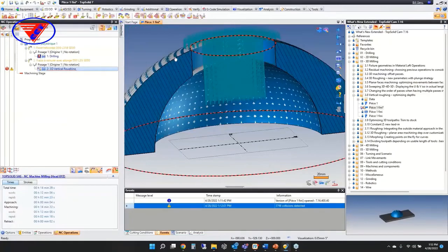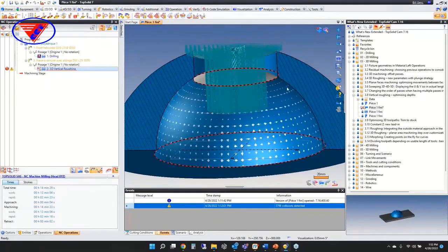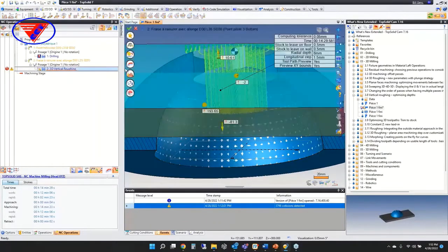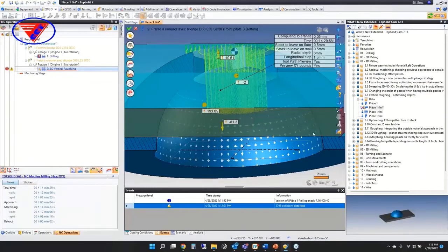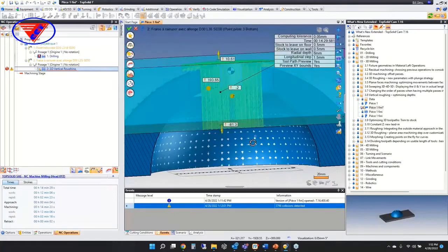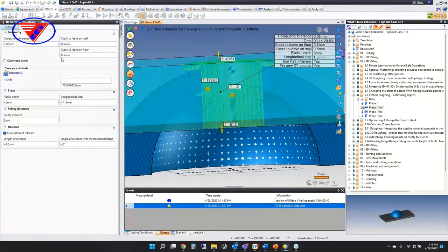So in vertical roughing, there was really no easy way to control that drilling over depth. Maybe we did it with extra geometry. I don't remember. Yeah, you can add an additional surface as something to stop it from going through, but you had to do manual work there. If you happen to have already roughed out this side and did a repositioning of it, it requires you to do extra work to really control the vertical roughing. So the improvement in 7.16 is right here.